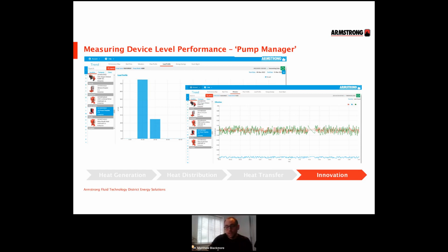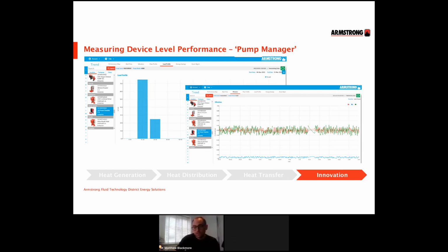In addition to that, a really good feature to note, every pump's fitted with a vibration sensor, and we collect vibration analysis. All rotating equipment have failure points. Each one will have its own vibration signature. So now we can start to actually predict the failure by seeing the signatures becoming apparent. This maximizes uptime, and it can carry out corrective action before it becomes a problem.